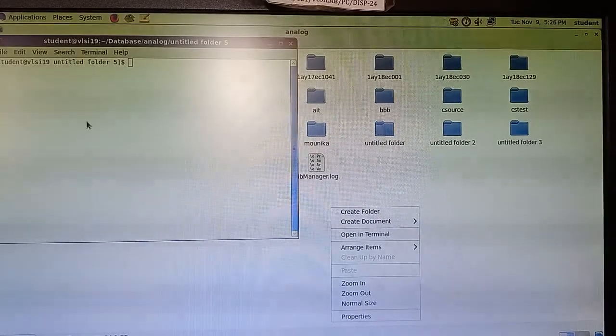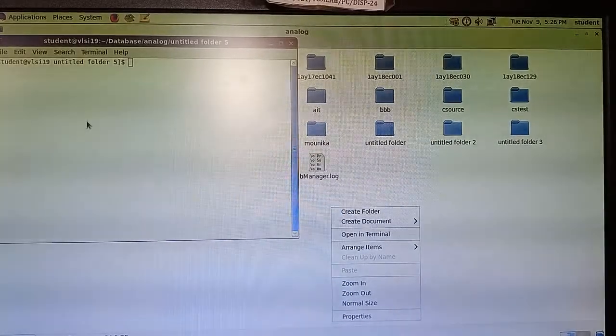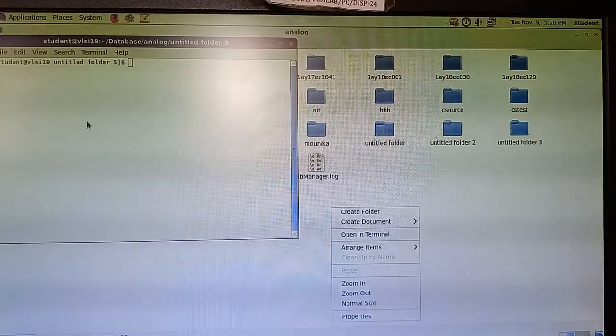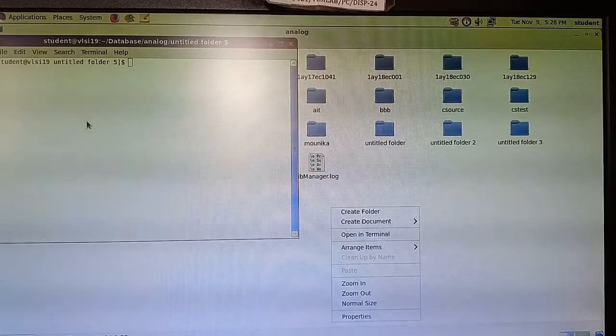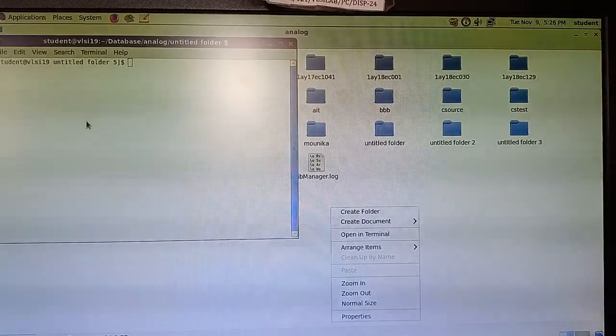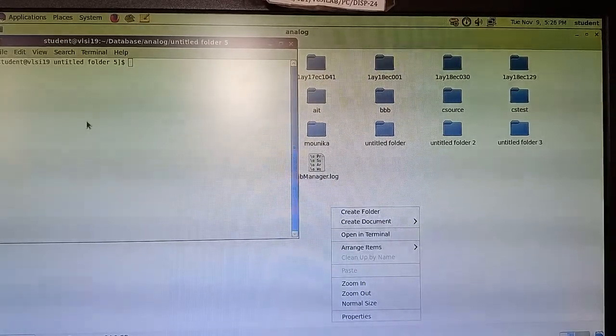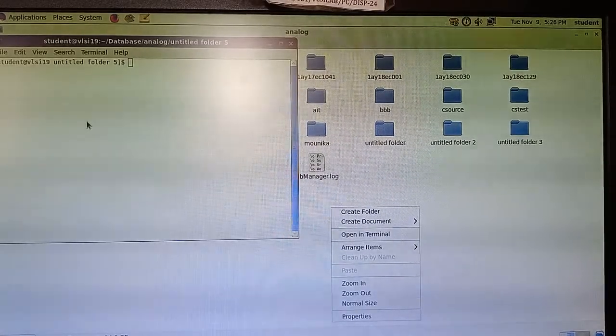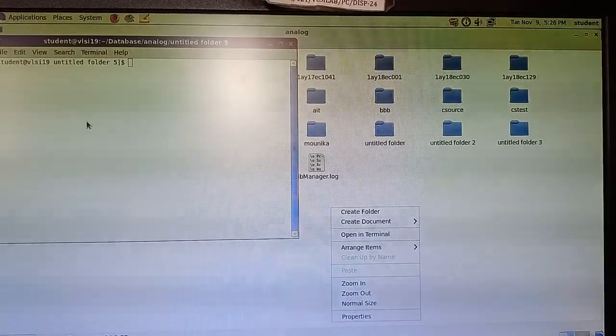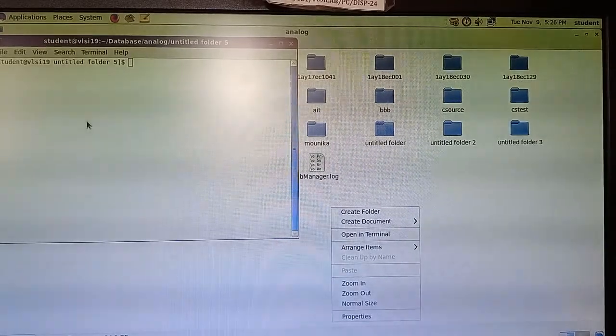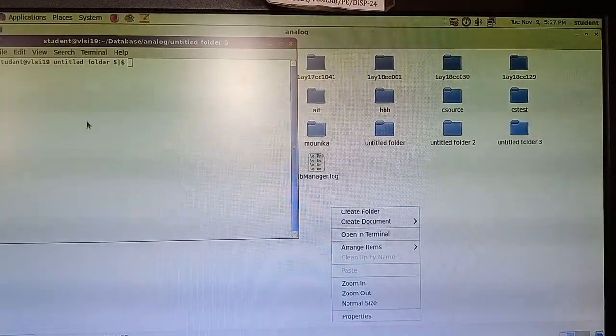First, we have to initialize C shell scripting. When you are working with EDA tools or a Cadence tool, you always need a Linux platform or Linux operating system. This Linux operating system has two basic scripting options: one is bash scripting and the other one is C shell scripting. Cadence EDA tools will always work with C shell scripting only. So we need to initialize C shell scripting.